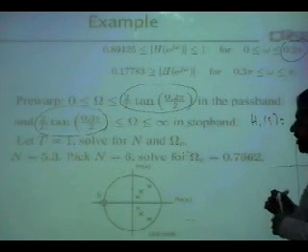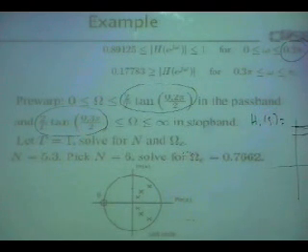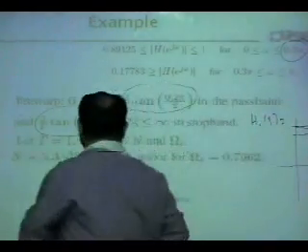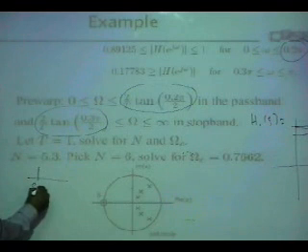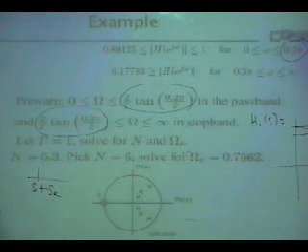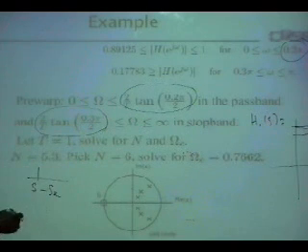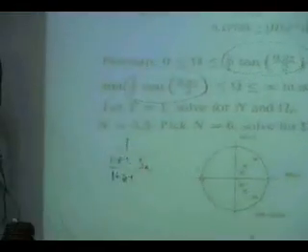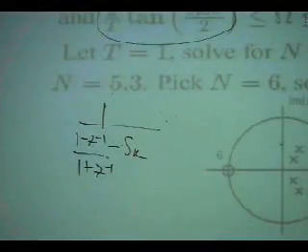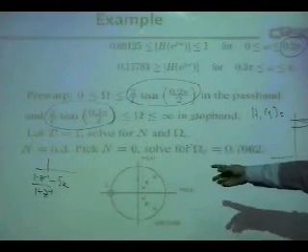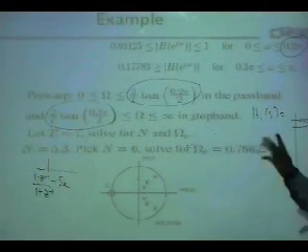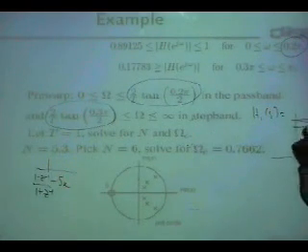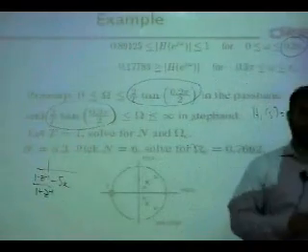And if you want to, you can exactly figure out how a pole will be transformed to this. And remember, I did that: if you know a pole in S domain, S plus Sk for example, or S minus Sk, whatever, you just go through, replace S by (1 minus Z inverse) over (1 plus Z inverse). Go through and you can exactly figure out where a pole in S domain will be placed in the Z domain by just doing a little bit of mathematical manipulation, which we did. Okay, I think it is (1 plus Sk) over (1 minus Sk) or something. So this will be the location of the pole. So you can find the location of the pole as well.